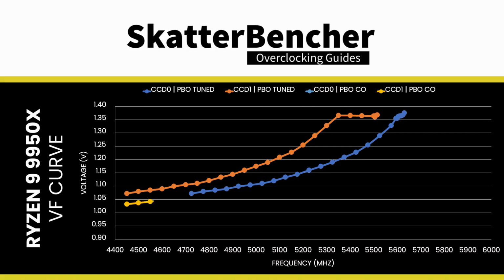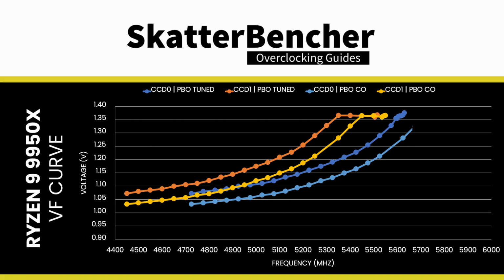If we set a negative curve optimizer, we can shift the entire voltage frequency curve along the voltage axis, and suddenly we need a lot less voltage for every operating frequency. For example, for 5 GHz we needed about 1.11 volt on CCD0 and 1.175 volt on CCD1. But with a negative curve optimizer, now we only need 1.066 volt on CCD0 and 1.12 volt on CCD1. Moreover, the frequency is also boosting higher.